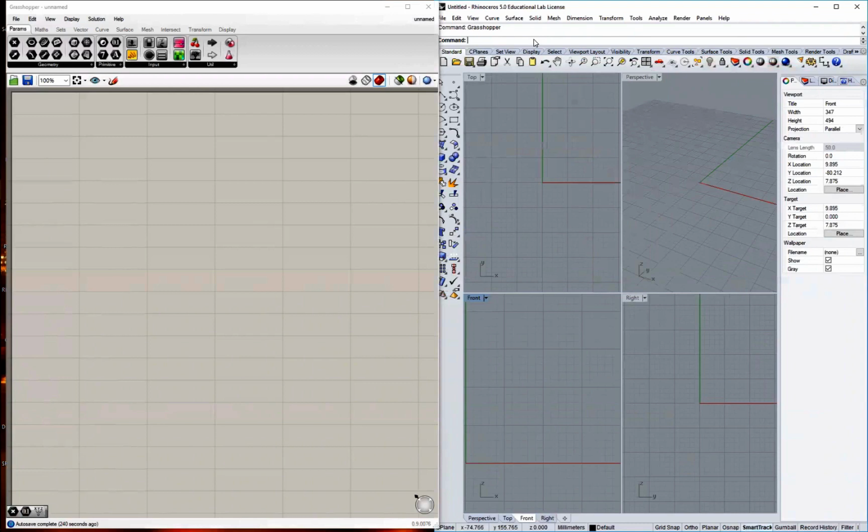Now, a lot of things about Grasshopper and Dynamo are very similar. So many things are going to look very familiar. They are almost so familiar that it's confusing, in that they operate just a little bit differently. For example, as opposed to a library pane over here where we click on nodes, we have a ribbon where we drag nodes down into the graph area.